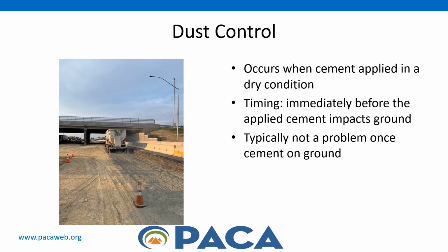If utilizing the cement slurry application, it's important that the slurry be dispersed uniformly over the subgrade area so that it does not run off or pool. Sometimes it's necessary to construct berms along the edge of the treated area to confine the slurry.